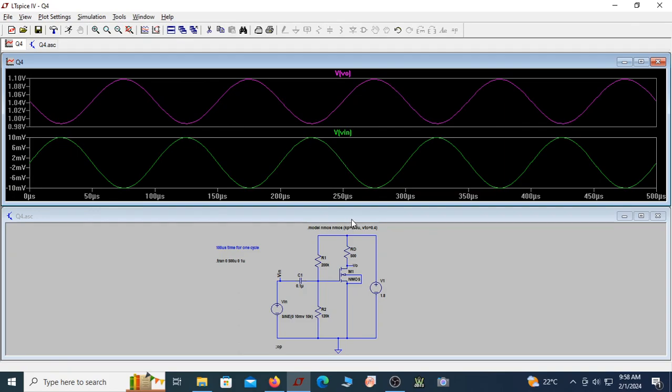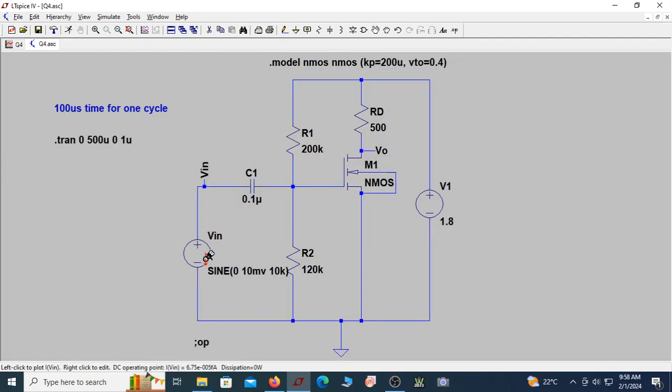To do the frequency response, we know that we have to change the frequency from a very low frequency to a very high frequency, and we want to see how this circuit responds for those frequencies. Does the gain remain constant? Does the gain vary? After what frequency does the gain reduce, or during what range of frequencies will the gain remain constant? Since you are changing the frequency, I cannot use a source which has a single frequency.